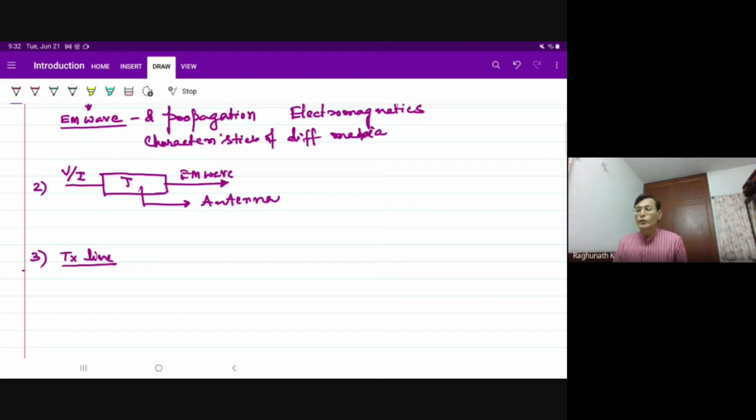Whenever we want to use a transmission line, I need to have a subject that tells me what is gamma, alpha plus j beta, for this. Alpha is the attenuation constant, beta is the phase shift constant, and it comes to a given line through the basic parameters of that particular line called R, L, G, and C: series resistance, series inductance, shunt conductance, shunt capacitance.